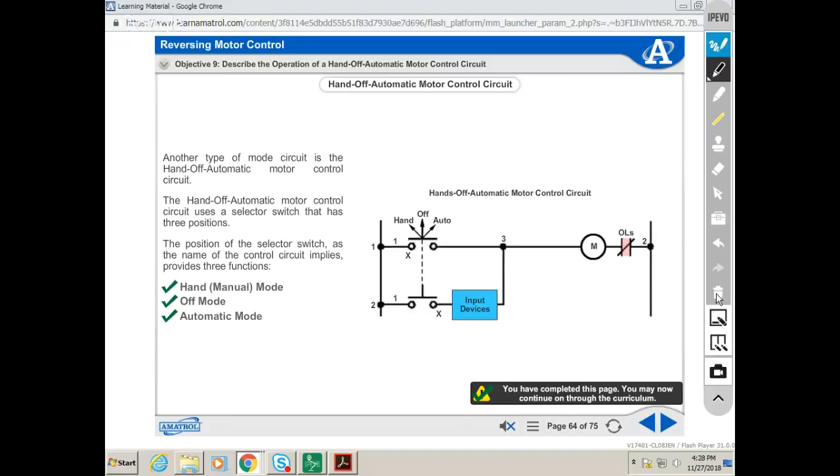In a PLC application, if you wanted feedback from a motor that it actually started, you would use that aux, and instead of tying it into a start-stop circuit, you would tie it into an input on the PLC, and then the PLC would see that I sent a signal out to turn the contactor on. It closed and sent a signal back to me that said it did close. We're good. We'll keep running the motor. Does that make sense? If I lose that feedback while the motor is being told to come on, then I know it tripped because the overload's tripped and dropped out the relay. So then I would use that for a feedback device. Make sense?